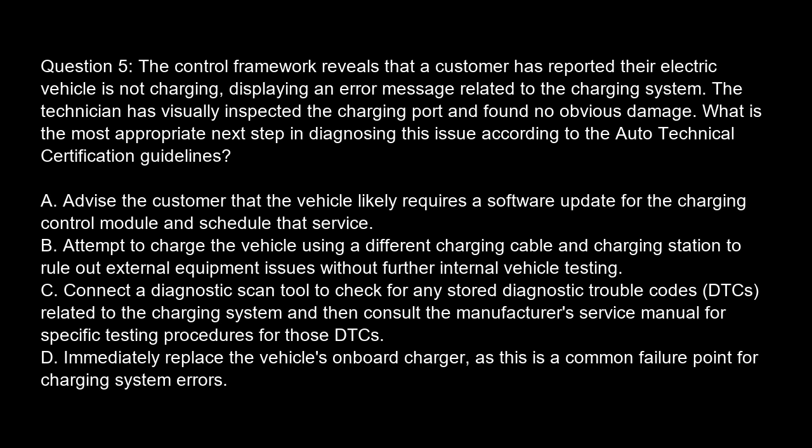Option A. Advise the customer that the vehicle likely requires a software update for the charging control module and schedule that service. Option B. Attempt to charge the vehicle using a different charging cable and charging station to rule out external equipment issues without further internal vehicle testing.